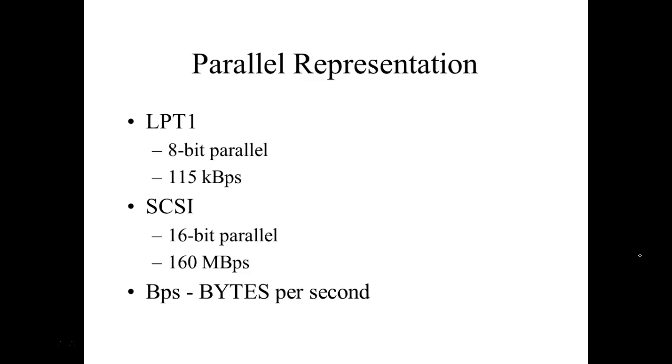Because when I connect to a computer, I'm connecting through what? Serial, yeah. Even HDMI is serial. It's just extremely high speed, but it uses differential instead of this guy right here. This guy uses ground, so this is still fairly slow, right? Resolutions on this, I think we got up to 1024 by 768 pixels. That was the fastest this guy would run. And now they're talking about, what, 4K? Yeah, that's definitely HDMI, but it uses differential and it doesn't use a common.